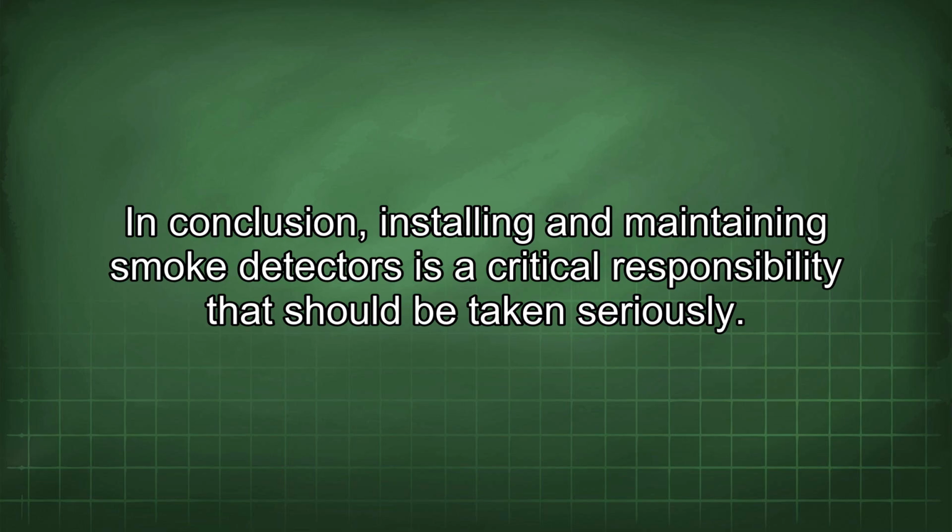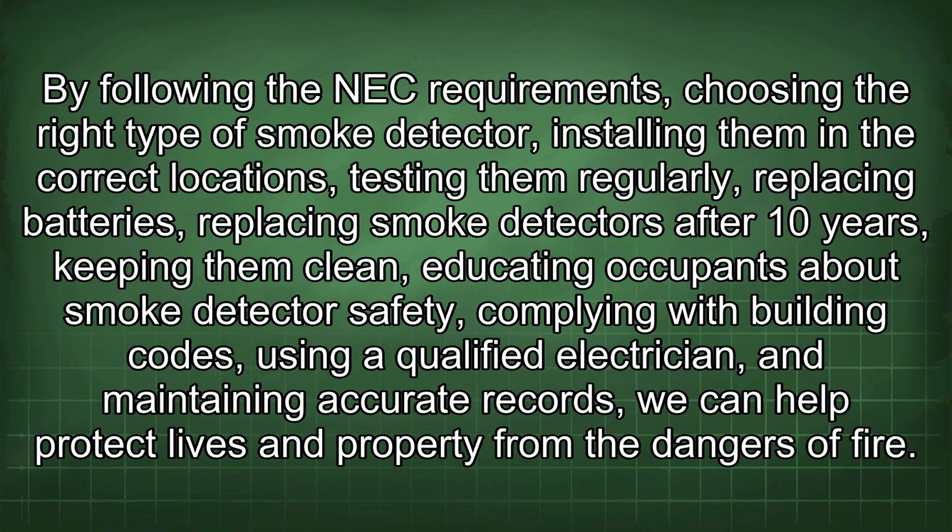In conclusion, installing and maintaining smoke detectors is a critical responsibility that should be taken seriously. By following the NEC requirements, choosing the right type of smoke detector, installing them in the correct locations, testing them regularly, replacing batteries, replacing smoke detectors after 10 years, keeping them clean, educating occupants about smoke detector safety, complying with building codes, using a qualified electrician, and maintaining accurate records, we can help protect lives and property from the dangers